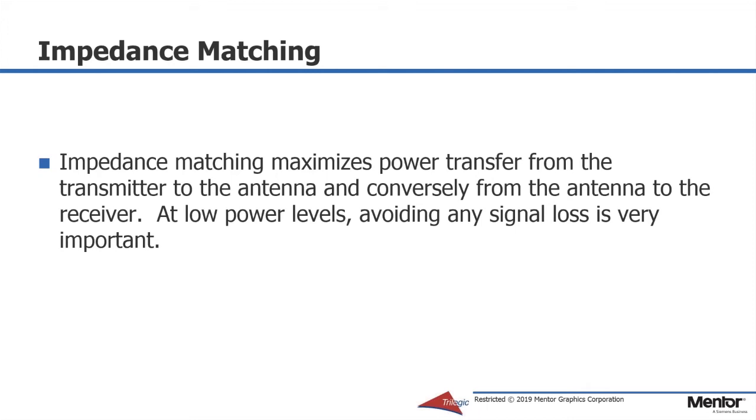And at low power levels, like we're dealing with in IoT, legally under a watt in Europe and in America, and in most of the 217 countries around the world that have similar regulatory standards, but normally we're even much less. For example, in the Z-Wave standard, we are very close to 1 milliwatt or 92 dB microvolts. Very, very little power.